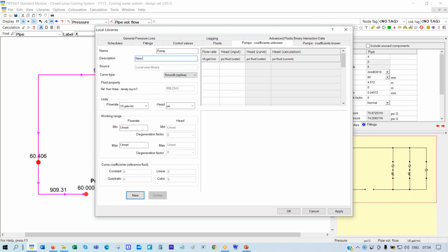This new pump. I put the values in. What I had was 900. I needed 16.696. I'm going to input the actual point from the pump performance curve, because the pump performance curve will be slightly bigger because I will choose a pump that's slightly bigger than the smallest pump that I can get away with.